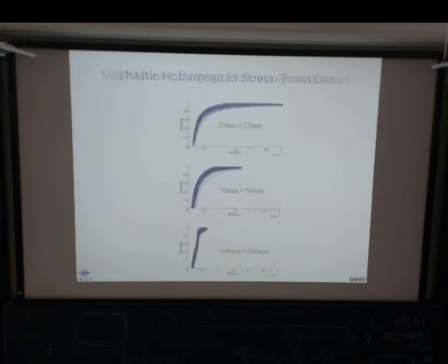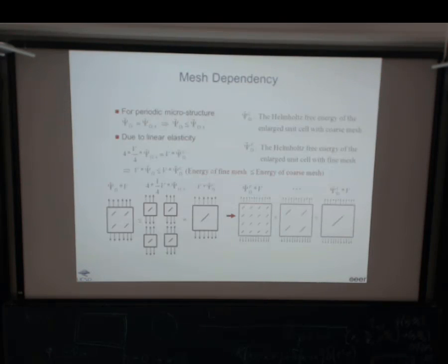It really happens this way. You look at the damage curve at the given strain, the damage is higher statistically in the bigger samples than the smaller samples. So Monte Carlo does show you the similar trend. Bigger samples fail easier. So what do we do?